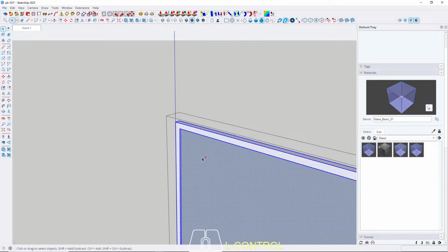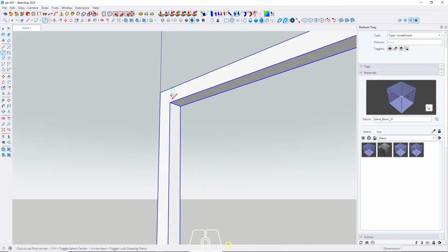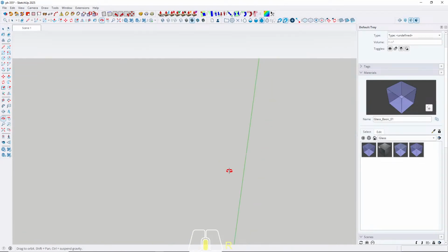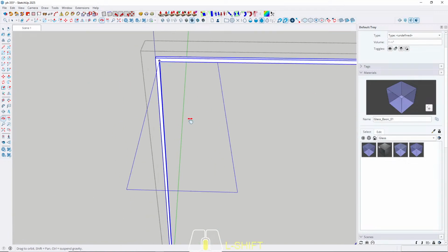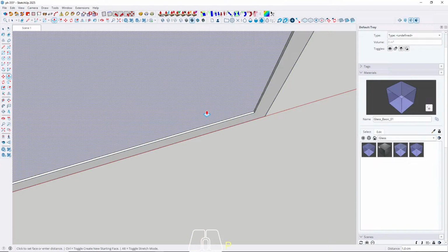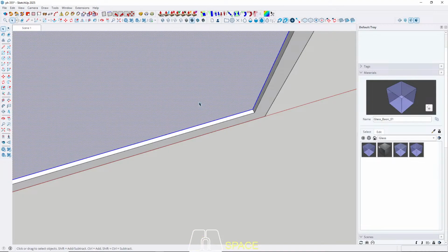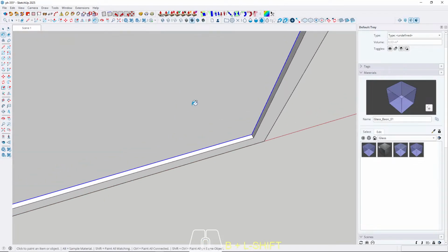It's very important to make a thickness on the door because it will affect the rendering result. So we have to be aware of the detail in your design, like this, and make a thickness at least 0.5. Make it group and then apply the glass material.